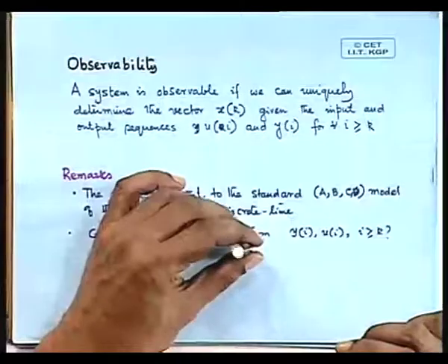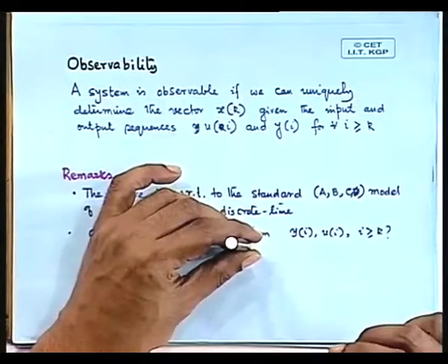That is, suppose the system started from k. Now if you are given all the future inputs and outputs, can you, using them, compute what was xk? It is a kind of an initial state problem, right. So if that is possible, then the system is said to be observable, right. Whether you can solve out the state from which it started.